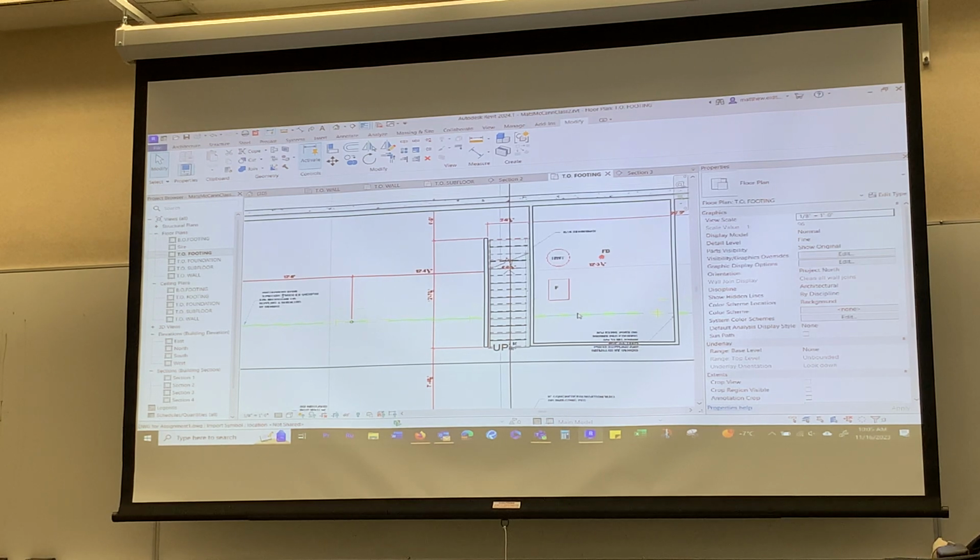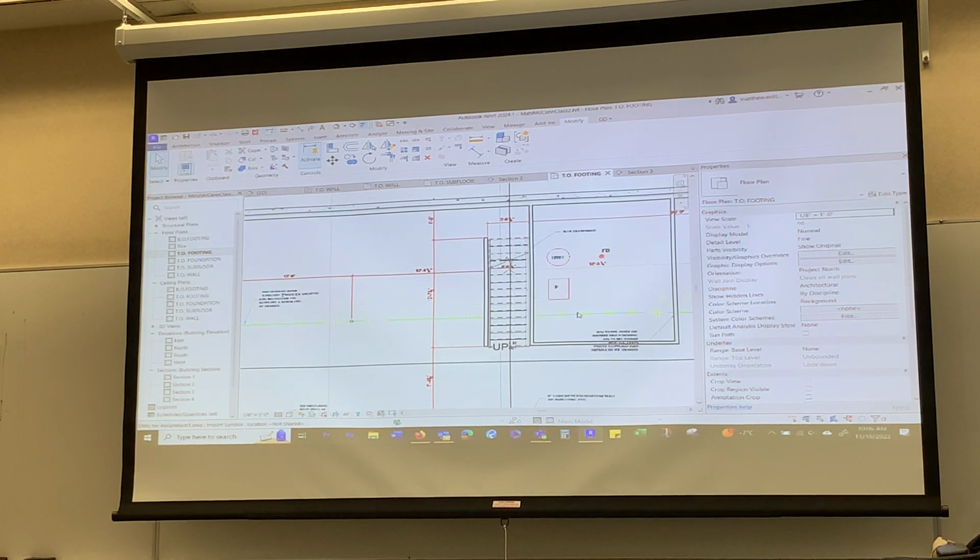So the width of the stringers, it's a family within a family. This is what I changed, right? Yep. Duplicate it first, or you're going to be in trouble. Duplicate it and rename it as a stringer 1.5 width. And what you're doing is you're adding that family to the other family.